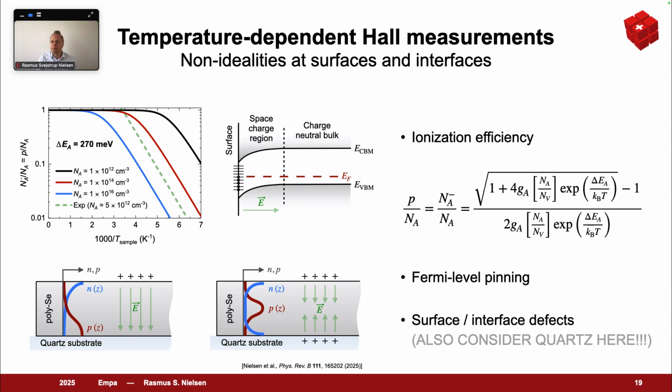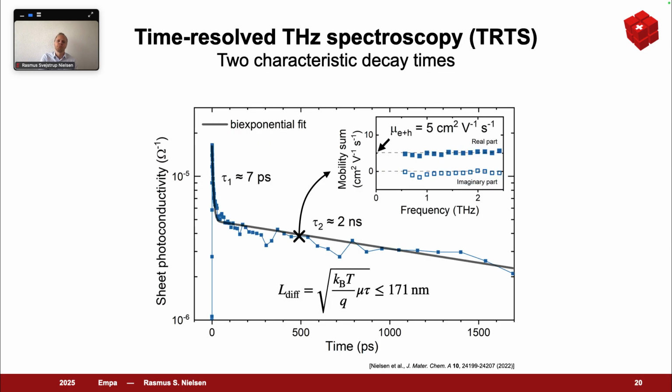And not only that, but such depletion effects may also explain why the apparent recombination lifetime was very high under low injection conditions, as the 2 carrier distribution functions have a quite small spatial overlap. As a result, the density of electrons and holes actually able to recombine with one another is low in comparison to the high injection case, where the distribution functions will smear more out as surface defects are saturated.